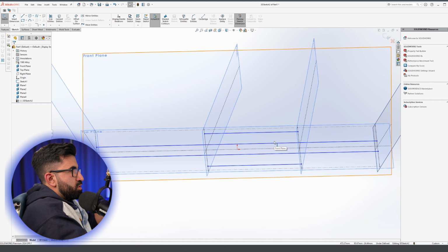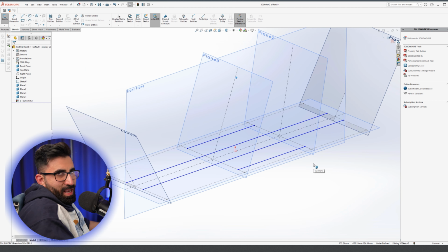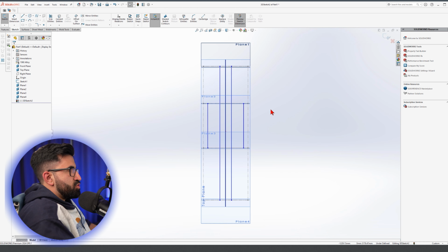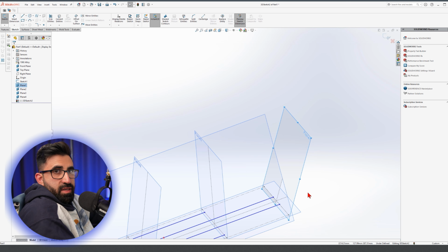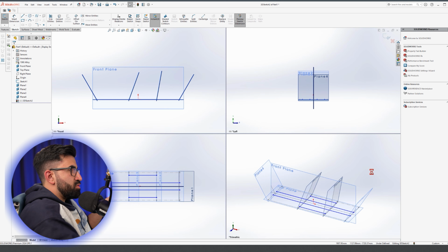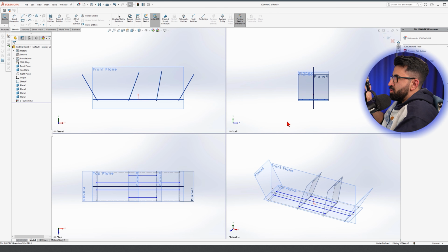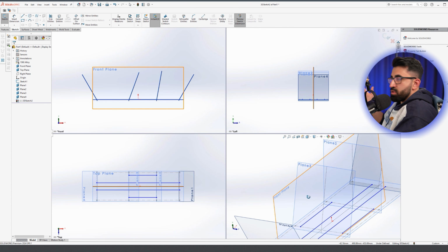Now we just drew the vertical lines. Let's just go up in the Y direction and turn it into an actual 3D sketch, right? This is a good trick that I'm going to do. Right now, I am going to add lines on this plane. I'm going to draw 2 lines that sit at an angle from each other on the plane 1. The way I do it is I press the space bar on the keyboard and I split my screen in 4. Now I get to look at the YZ, XY, and the XZ plane at the same time. And on top of that, I have the isometric or the free view to see what's going on here too.